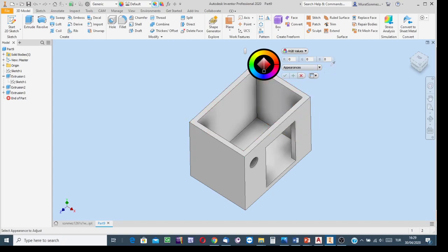I'm going to use this one. From this appearance list, select the color option and then indicate the surface. For instance, indicate this outer surface and then select green from the ring as the color option, and then moving the square over the diamond, you can make it lighter or darker, you know this. Click on apply, but here I'm going to have not a dye, not a color, but a surface effect, mosaic.